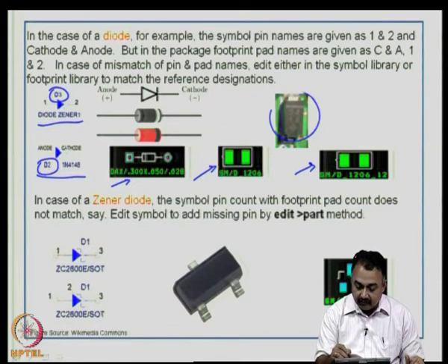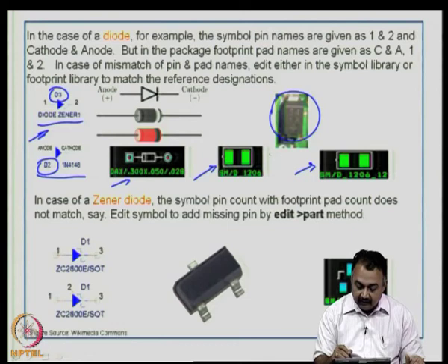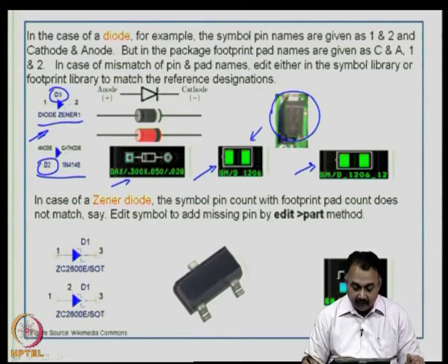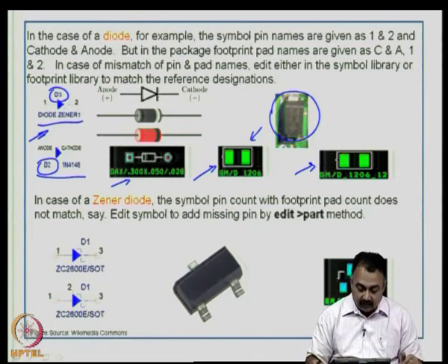This is a surface mount device, and therefore, you have to bring the symbol for this particular component diode like is depicted here, and then attach it or link it to the surface mount footprint pattern. So, that this information is carried nicely into the layout section.